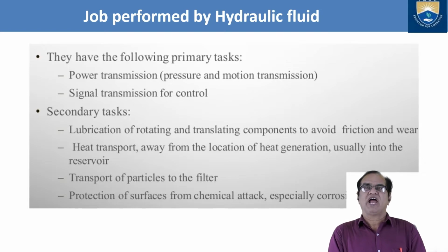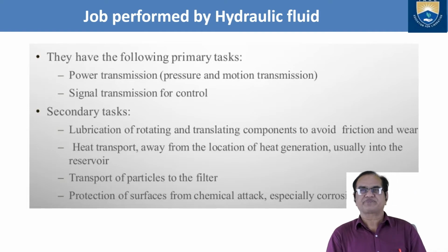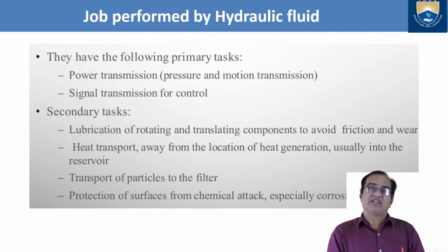Next is the job performed by the hydraulic fluids. So what are the jobs hydraulic fluids perform? They have the following primary tasks: power transmission, pressure and motion transmission. So the first work is to transfer the pressure and the motion of the system, and then signal transmission for control. If you want to make something happen, you have to give the signal, so hydraulic fluid will open or close the system. These are the two primary tasks, but we also have some secondary tasks like lubrication of rotating and translating components to avoid friction and wear.